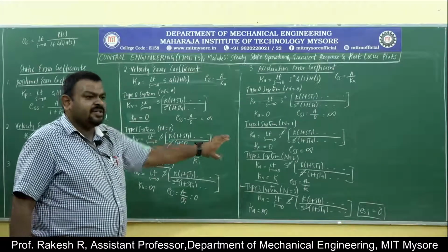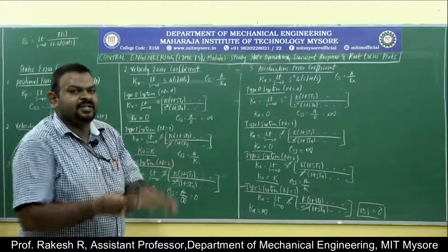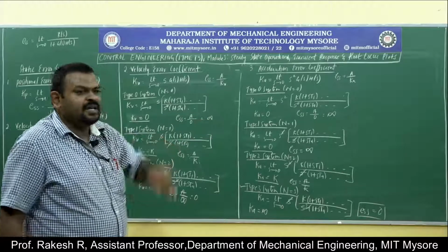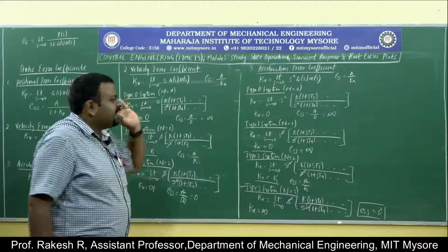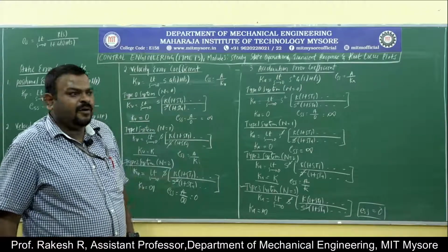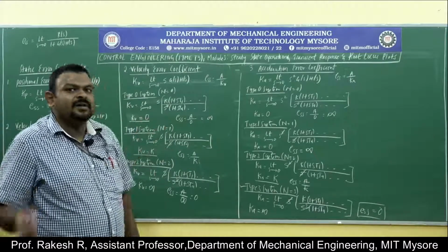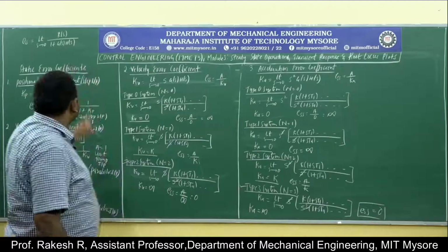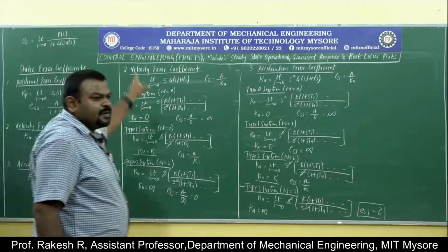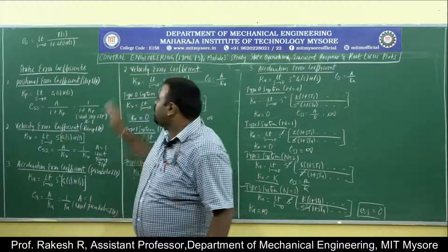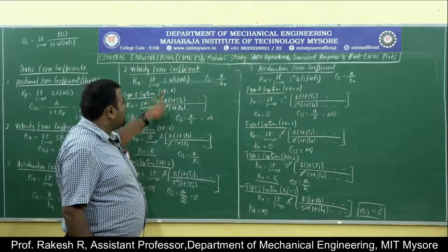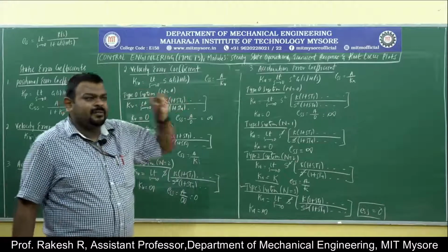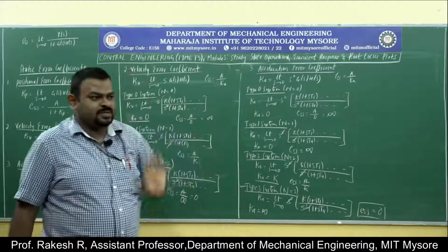By making use of steady state error, you can adjust and make the system stable. So this is the steady state analysis for different kinds of input. Here there are two things. One is R(s), that depends upon the input type, and another one is the open loop transfer function. Open loop transfer function is just a pole at origin, that is type 0, type 1, type 2 systems. That's all.